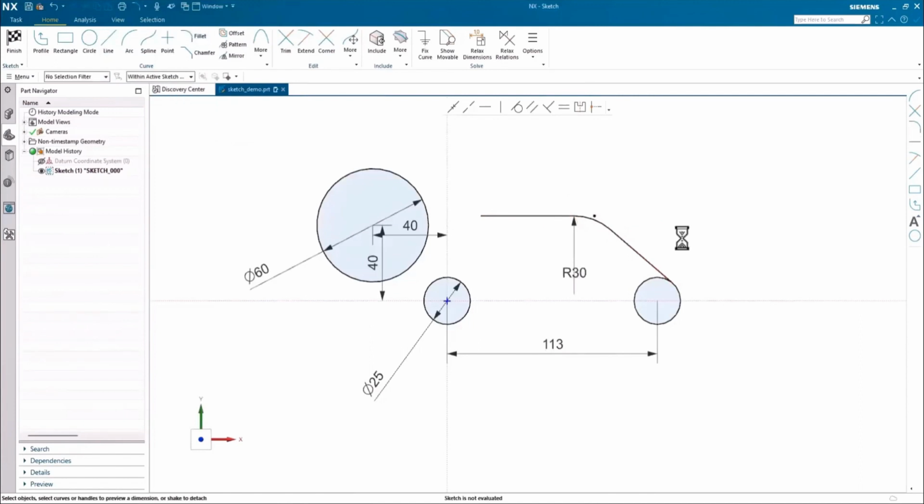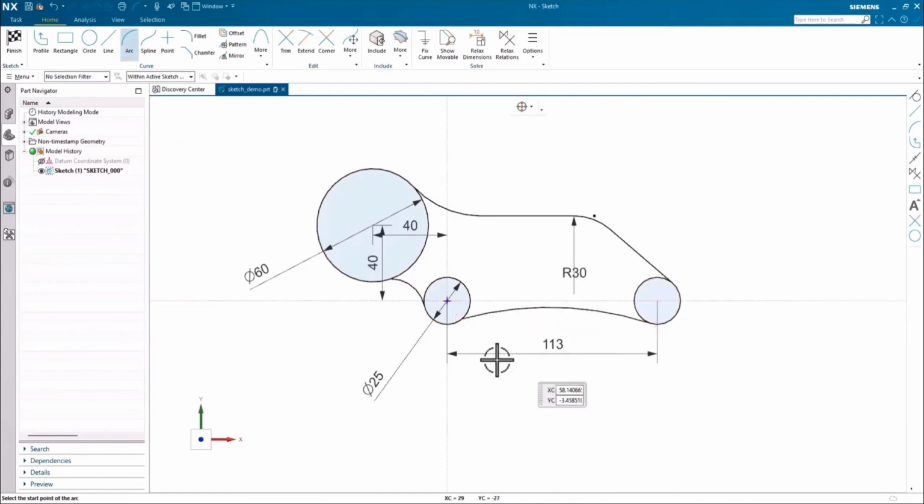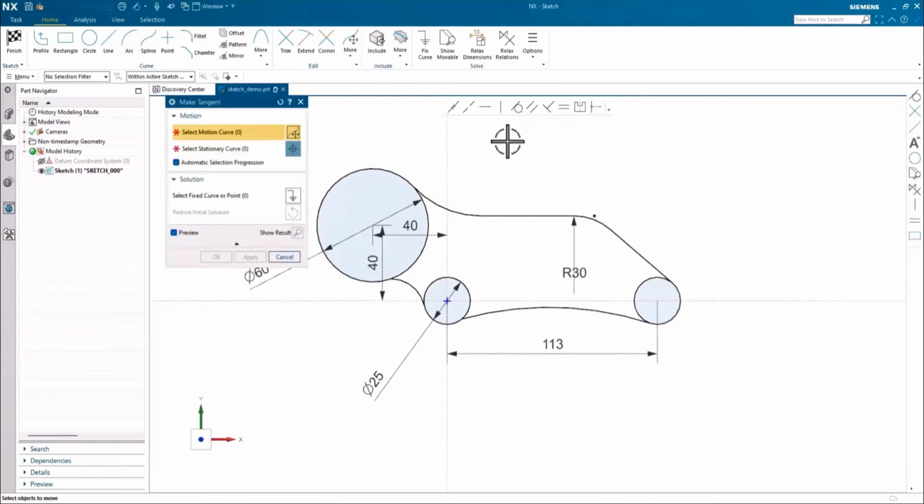As we generate that fillet, you'll notice that because I had a size, it put the dimension, but it also puts a dot there. That actually is the intersection point, right? So if we untrim that, it keeps it there. So if you want to dimension to that, it makes it very easy for the user. Also, we have both the selection intent and the point menu, so you can turn on the different types. Like in this case, I need the point on curve because I'm doing a lot of this where we're connecting these arcs to the circles. So you have control over those.